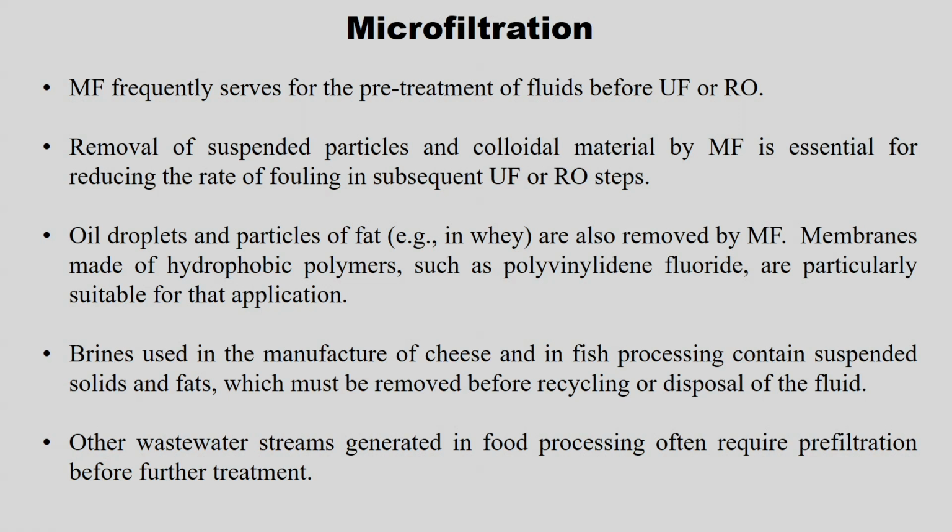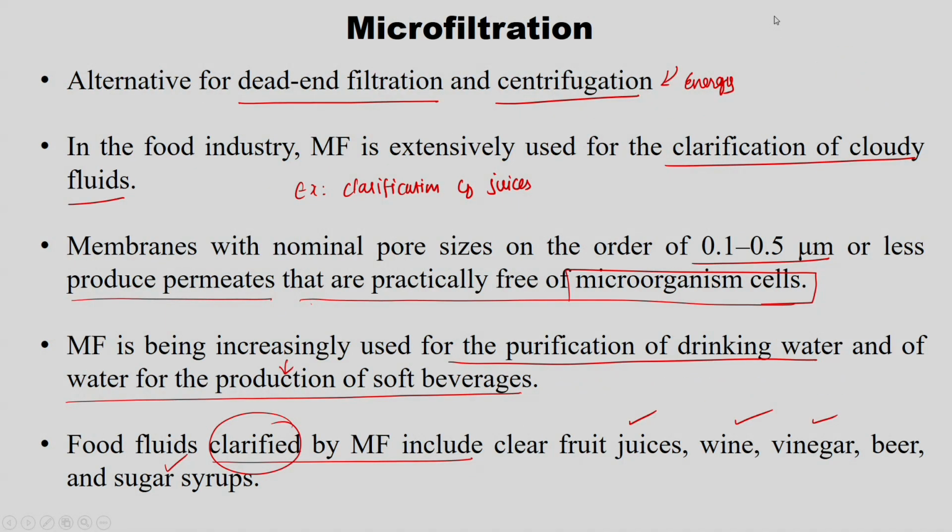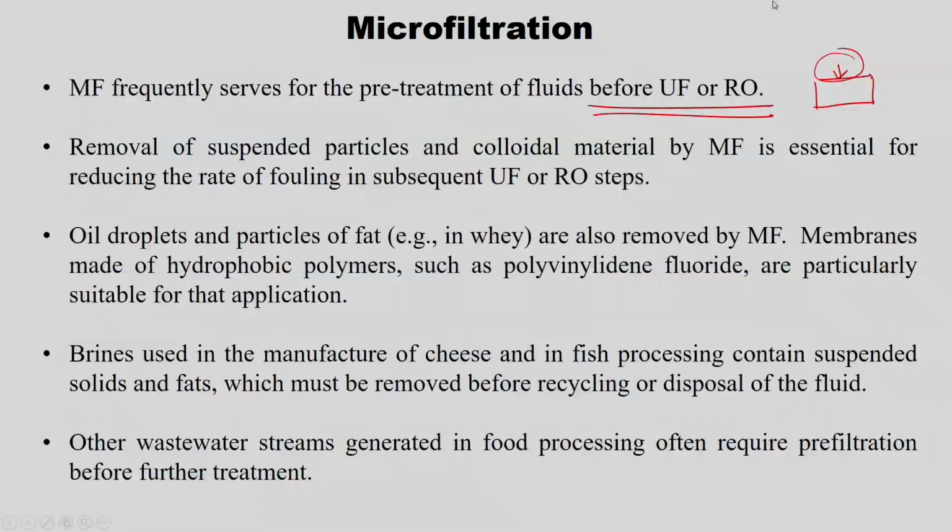Microfiltration frequently serves for the pre-treatment of fluids before ultrafiltration and RO, right. See, the membrane process is nothing but a filtration process. Instead of directly going to ultra or RO, here the pore size used is 0.1 to 0.5 micrometer. So, whatever bigger size molecules there are, they get retained in the microfiltration technique. That is what serves as the pre-treatment for the fluids before ultrafiltration and reverse osmosis.